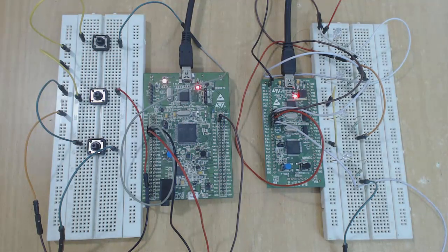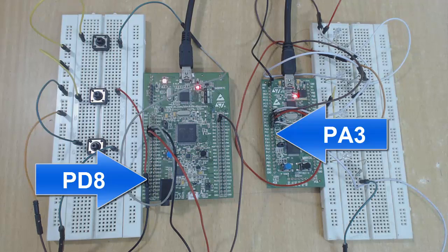The one thing that we have left is a connecting wire between the first board's transmitter pin and the second board's receiver pin. And now we can do that. We have the PD8 pin on the first discovery board, that's the transmitter pin. And now we have the PA3 pin on this second board, that's for receiver. So what we have to do now is connect a wire from PD8 to PA3 pin. Let's do that.